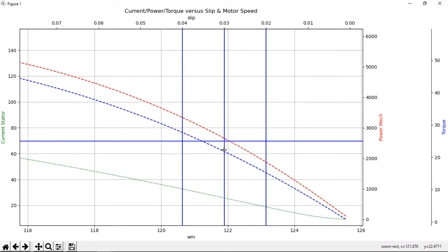It may be kind of slow to start because of that, and you may have some problems there, but it should start. The current is going up to about 25 or 26 amps maybe. And the actual power that we're generating is somewhere around 2800 watts.